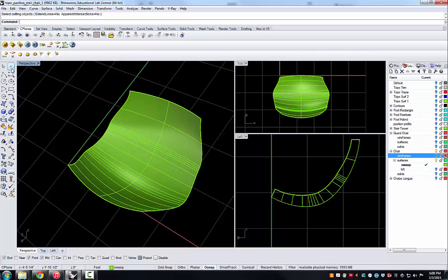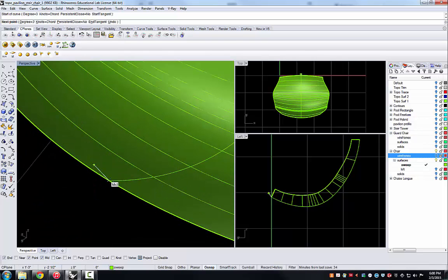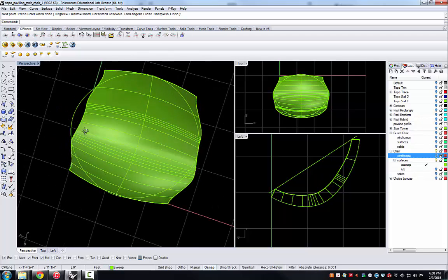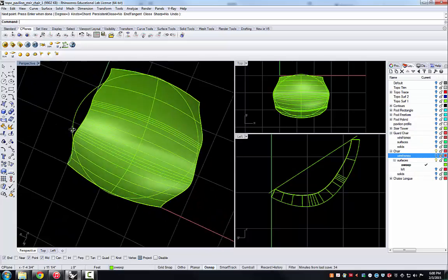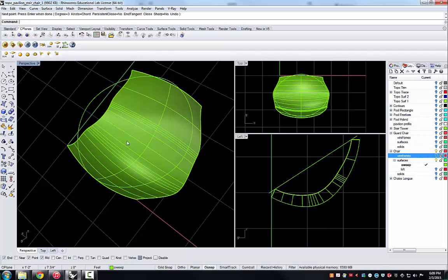And so we're going to use a simple interpolate points curve starting from the midpoint of the surface. You'll notice that I'm clicking on the midpoint of the surface. The point is showing up here in space on the construction plane. So the next midpoint places it there, this midpoint, that midpoint, and finally back where we started. And what that's done is created a very smooth curve. It goes off the edges of the wavy surface of the chair.